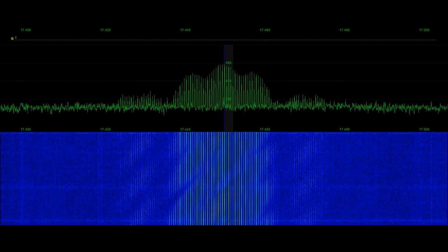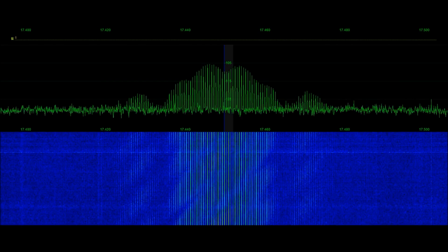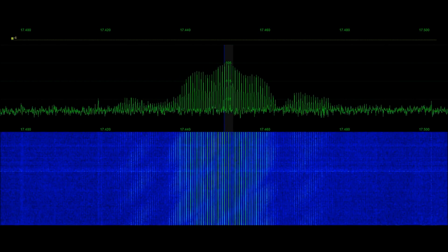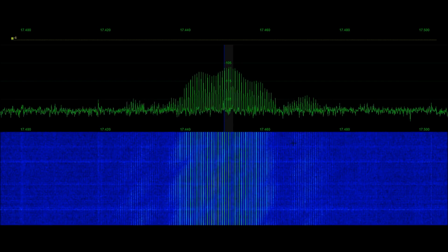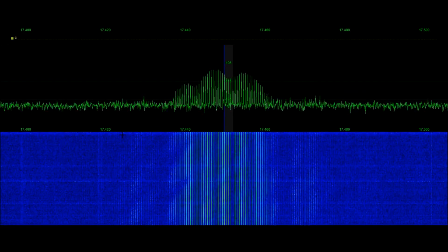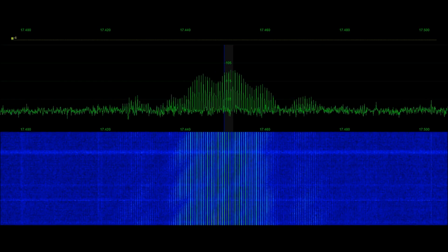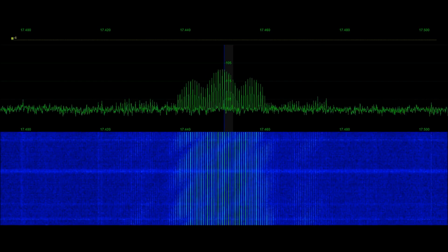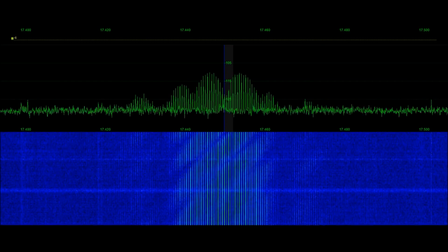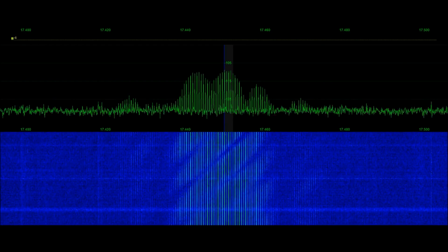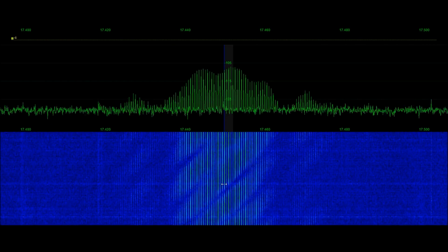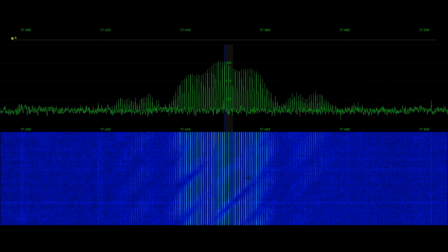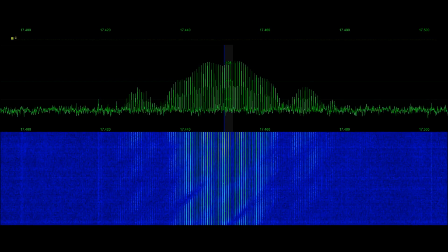That is a product of the receiver only. And as the signal builds back up, you can start to see the cosine lobe here in the coarse structure, and then the independent sidebands with less energy. So let's go ahead and zoom in, and we'll turn on the oscilloscope, and we'll see what these individual carriers are going to look like, as we are going to be looking at an audio component as reference to the center of the receiver through the beat frequency oscillation.